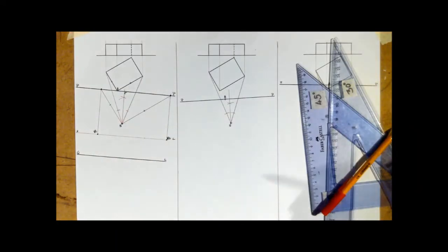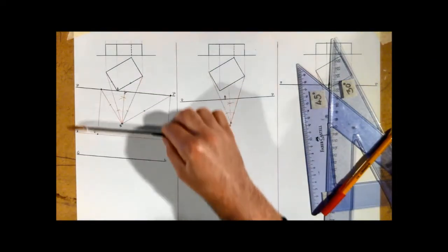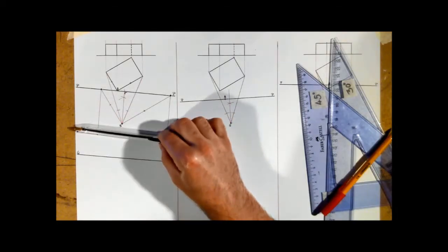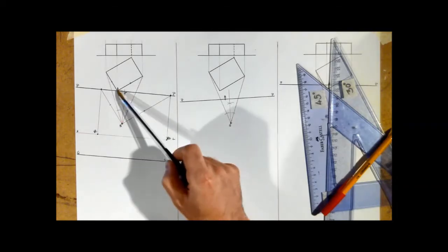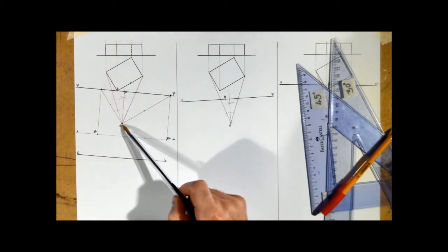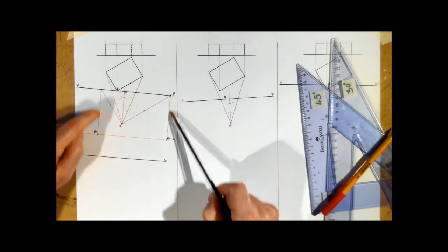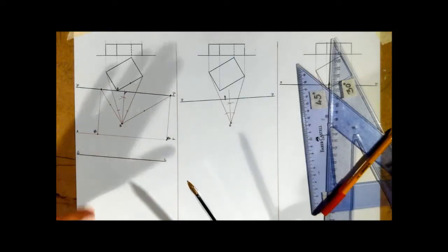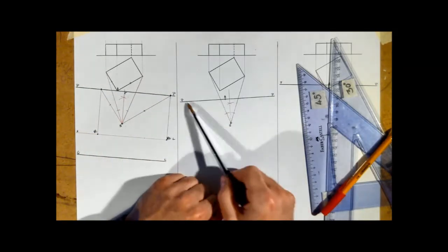Okay, so the steps that we did there, very simple. Parallel to the picture plane, we set up the ground line. So they are parallel with each other, and then the horizon line was 30 millimeters above our ground line. And also from the Spectator, we went parallel to the extreme edges, and where it hits the picture plane, here and here, drop it down and it gives us our vanishing points. Okay, those steps are always to be followed. They never really change, and the only thing that will change about them is how your picture plane is set up.